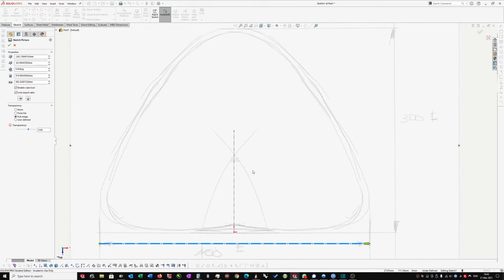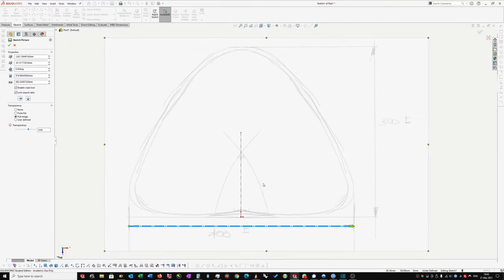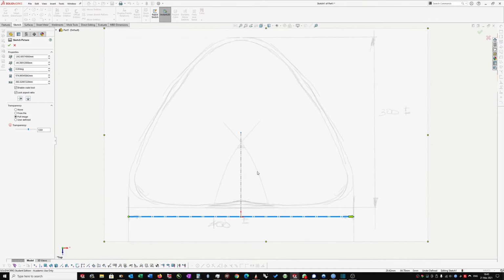I could drag it so that the origin point is at the base of this stool top, but that's not what I advise you to do. I think what you've got to do, well, I know what you've got to do, is actually give yourself some space at the bottom, and you'll see why in a little while. This is because surfaces need extra space.